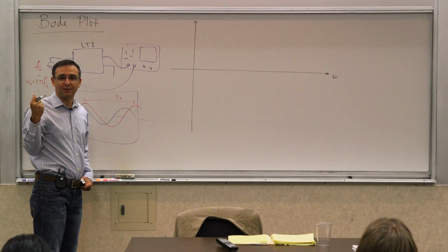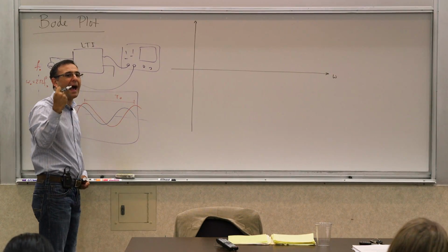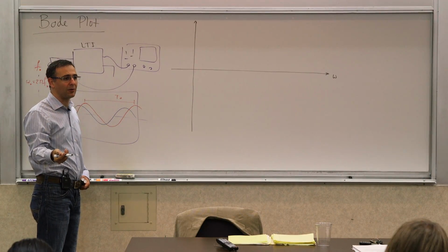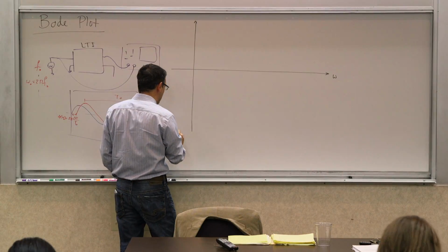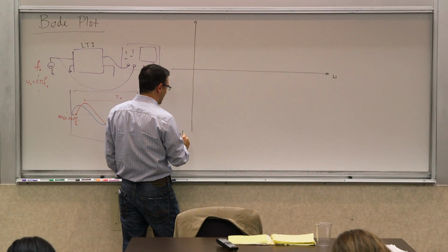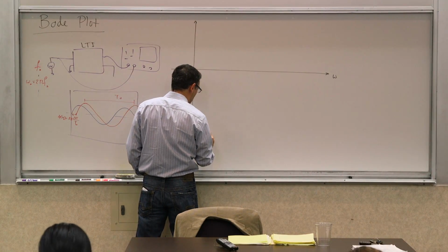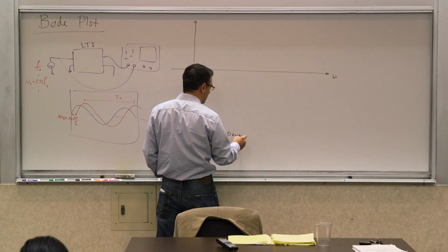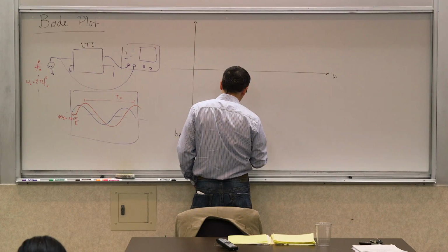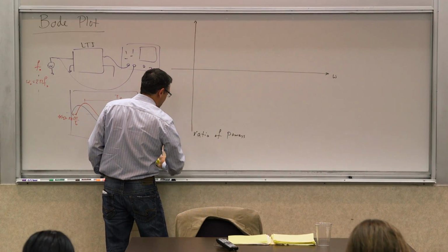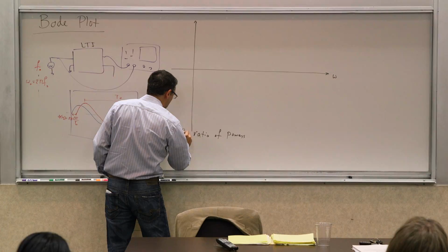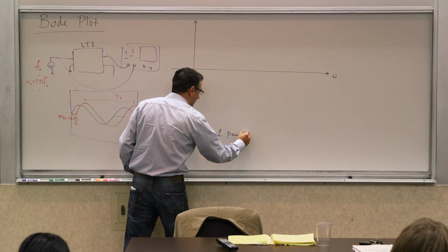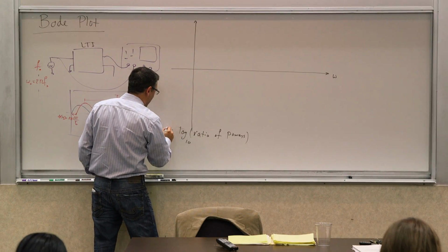It's measured in Bell. Bell is a ratio of powers, the log base 10 of the ratio of powers. So the unit of Bell is a ratio of powers, usually the output to input, or 10 log of that, let's say. I'm sorry, just log of that, log base 10 of that, not 10 log. Log base 10 of the ratio of powers is Bell.